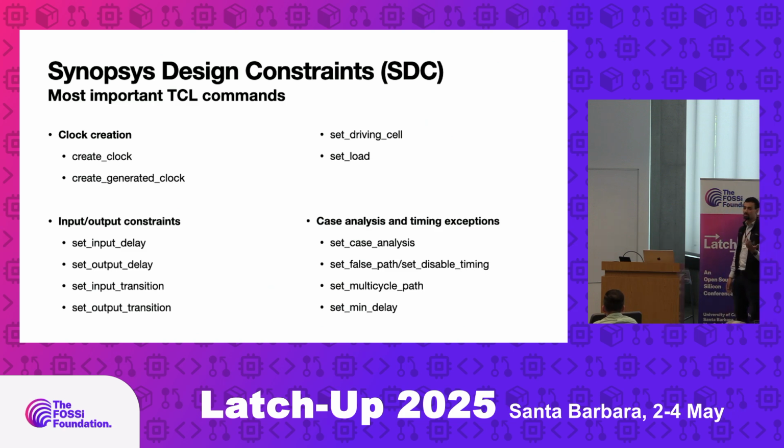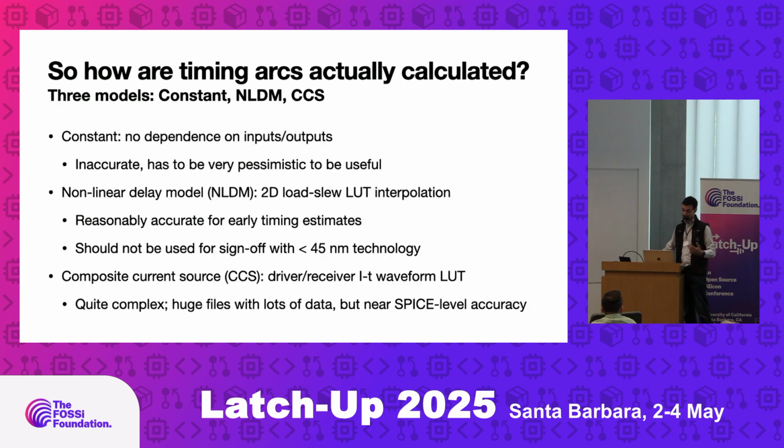So case analysis is where you assume, let's say you have some registers that are CSRs, maybe generated with PeakRDL, and these are set to a particular constant value. That may have an impact on the timing. Maybe you would be too pessimistic if you didn't consider that those paths were constant. And that's just another thing to consider. And then false paths, where there are certain paths you want to ignore. Multi-cycles, where it might take more cycles to get there, et cetera.